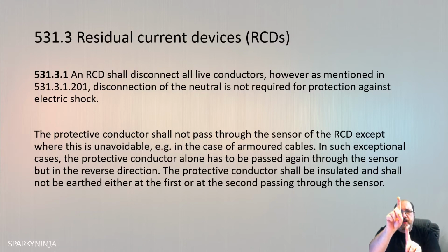What this is saying is, you've got your line going down and you've got your neutral going up, but at the load there's equipment leaking to earth, but within the cable going through one coil, like an armour, the earth is also going through the coil. So instead of running like you know with an RCD, you run your two live conductors into the top of the RCD, and then your live conductors going out, and your earth is completely away from all that. This is saying that earth is with those going through the coil. I don't know. I've seen RCMs go around cables, but RCDs going around whole cables, sheath cables. I guess that's what they're referring to here.